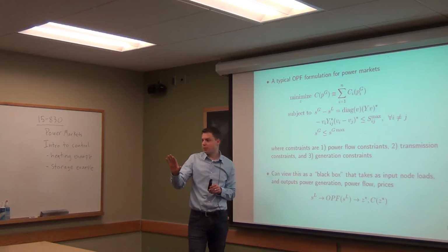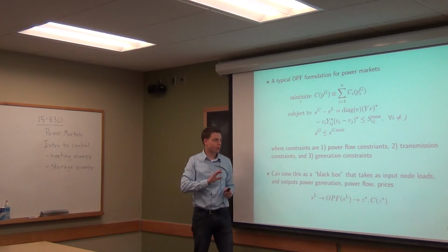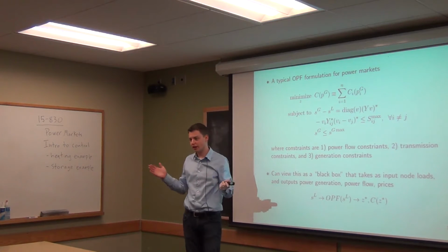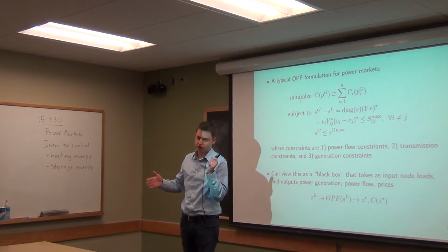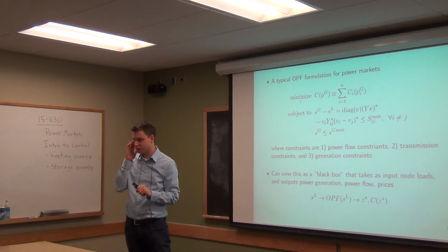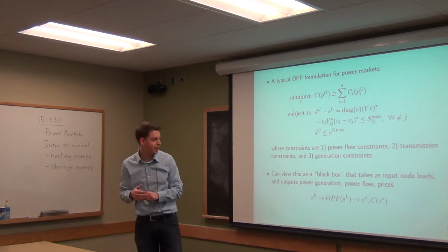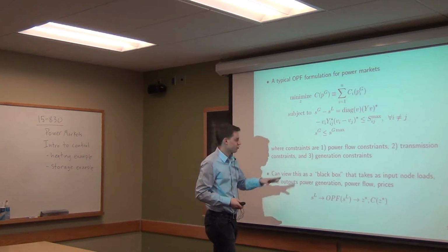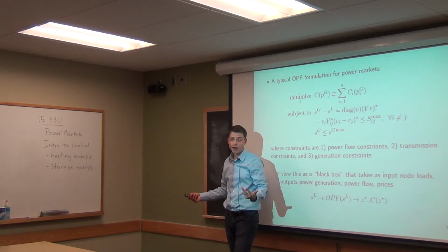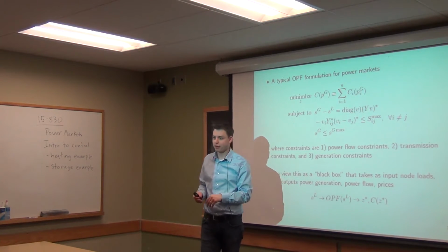This is just an example. There are other things you probably want to add here, as I mentioned, like maybe you have some constraints on voltage angles, for example. You can't have voltage angles too far apart, or some instabilities become concerns, so you constrain them in that sense. You'll probably also add constraints on reactive power, things like this. Generators can't necessarily produce a huge amount of reactive power, maybe.